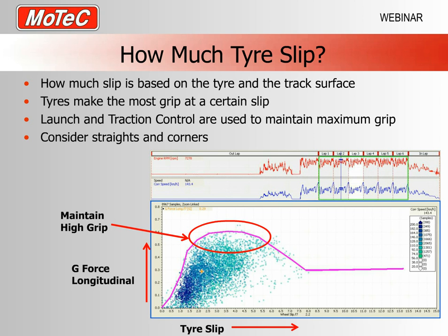The other thing you would do, just alluding back to my aim slip table with lateral G, is we could also use the comparison of lateral G. So when I'm going through a corner, how much slip am I allowed to make the car accelerate forward? And you'll find that will be a fair bit less. So this actual curve here, even for the one tyre, will move around depending on conditions.